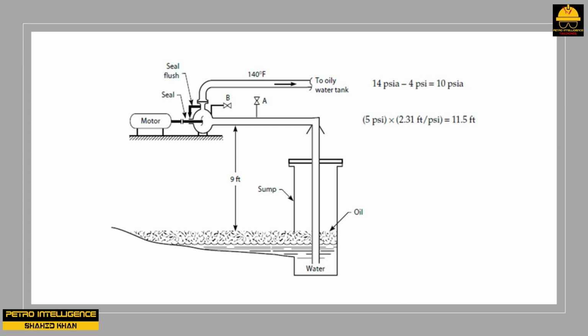the required NPSH. A pump that is lifting very cold water, with a very low vapor pressure, through a smooth, low frictional loss suction line, with a very small NPSH requirement, operating at sea level, where atmospheric pressures are high, can lift water to its suction by perhaps 30 feet. The pump shown in picture can lift 1200 GPM of water by only 15 feet. When the water level in the sump drops to 15 feet below the center line of the pump's impeller, the pump will cavitate. Where, then, does the available NPSH to a sump pump really come from?